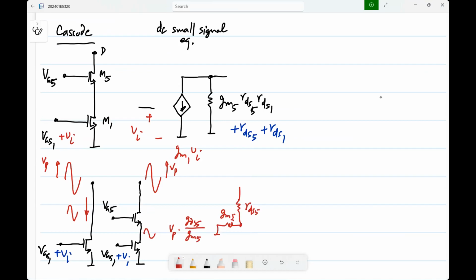Okay. So then you will get some sort of voltage division. So it substantially reduces the voltage swing here. Because finally this voltage swing times GDS1 is the incremental current, right? So the current has reduced. Essentially, it keeps this constant.